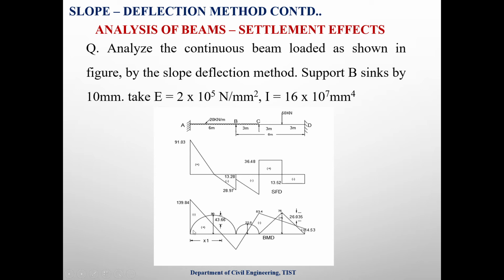Then mark the final moments. If it is in the anti-clockwise direction, that means that is negative. If it is positive, that means this is the clockwise direction. Then likewise, please draw the combined bending moment diagram.